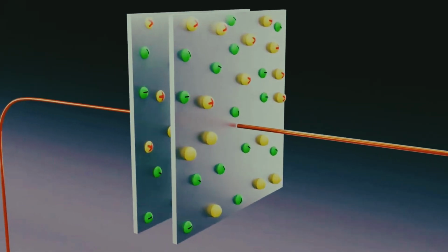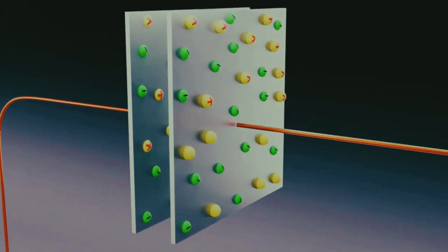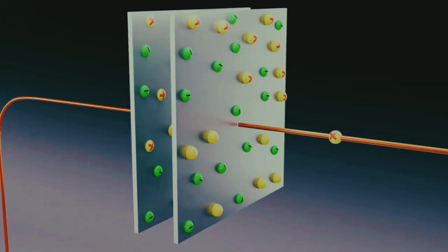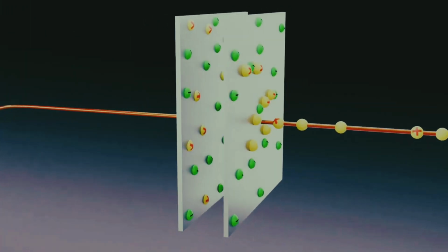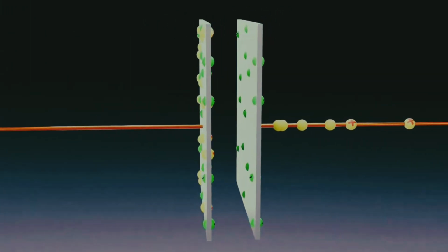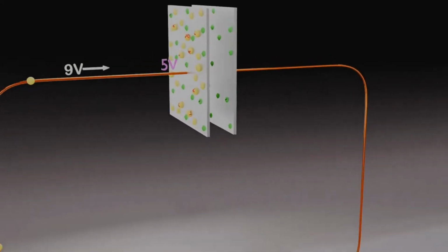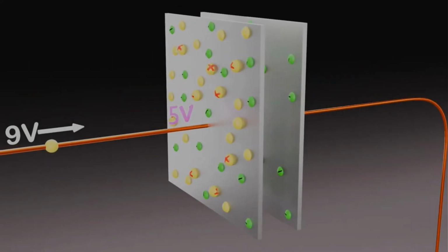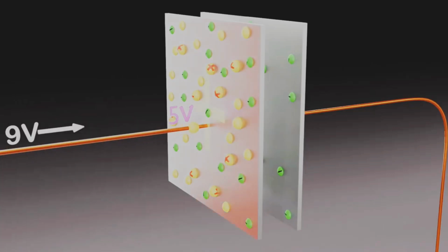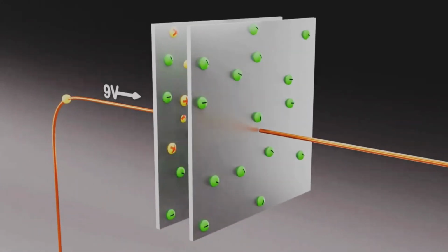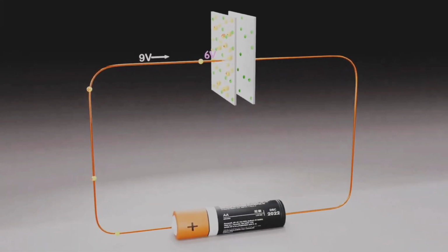The structure of a fixed capacitor is relatively simple but highly important for performance. The main components include two metal plates, electrodes, the dielectric layer between them, protective casing, and connection leads. The dielectric material determines how much charge the capacitor can store. For example, ceramic capacitors are small and stable, making them suitable for high-frequency circuits. Electrolytic capacitors can store larger amounts of charge and are commonly used in power supply circuits.